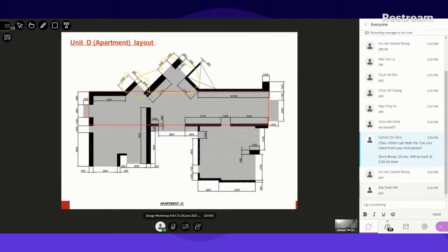You remember that I said that if our floor height is 3.5, if our clear ceiling height is 2.7, then you have 1.2 meters or so space between the ceiling height and then that. So basically, although you don't see, this concrete wall doesn't stop there. Now, if I look at this particular elevation, that's why I said it is very important for you to see this elevation here. It will be like that actually.